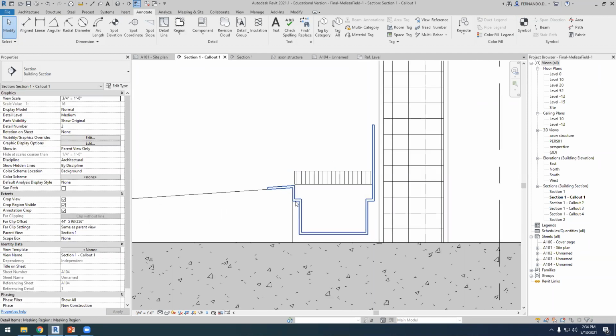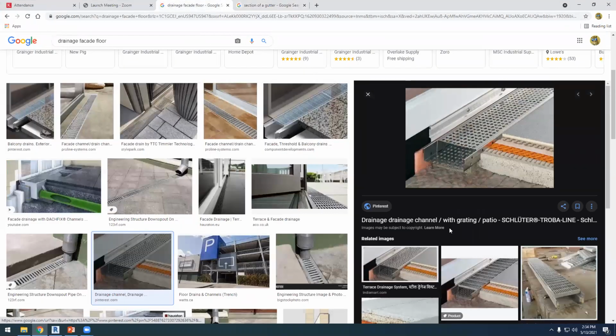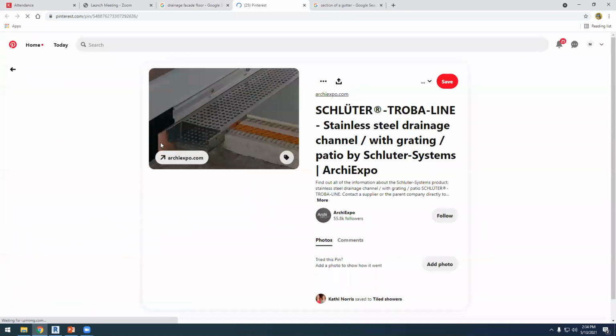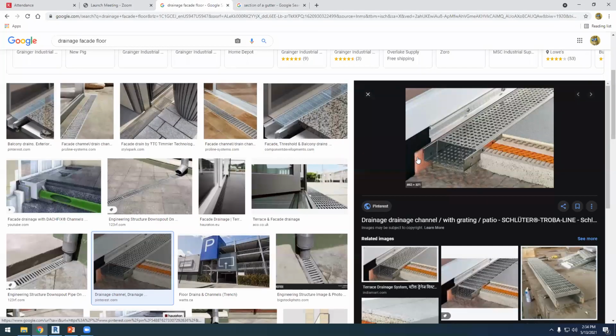This is not floating, so there is always something. Yep, like this. You see this pink or pinkish element. Okay, so this is always something elastic, because this gutter is made of steel, as you can see, or aluminum, and if it heats up, it can expand. So we always need something that protects the wall. Okay, so we have this element, which is like rubber, something elastic here and there.